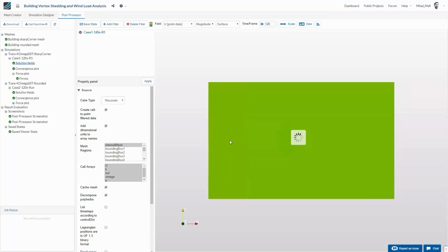and right now I just made the live demo about SimScale, and right now we're taking a look at the live results. Maybe something which is also interesting for you, Per, for this atmospheric boundary layer, I showed them that you can just upload the wind profile as a CSV file. And from our discussions, I know that a lot of other tools are providing these wind profiles, right? So if you're based in Oslo, you can just export the main wind direction and the wind profile, right?